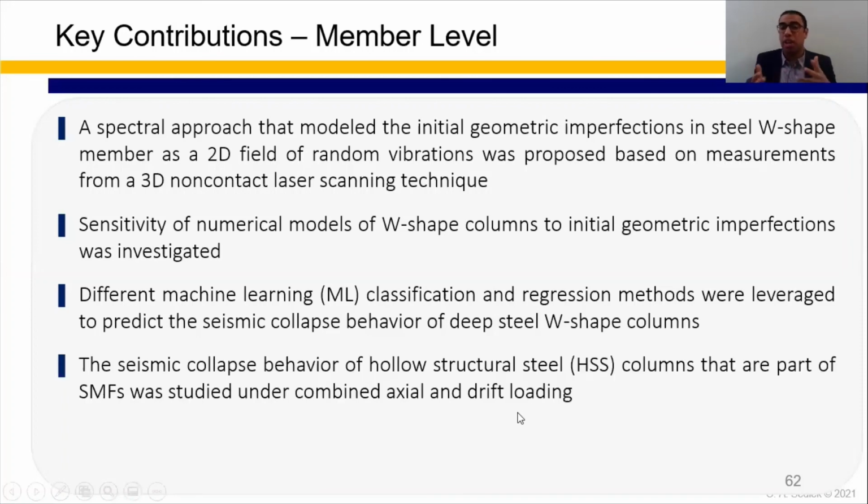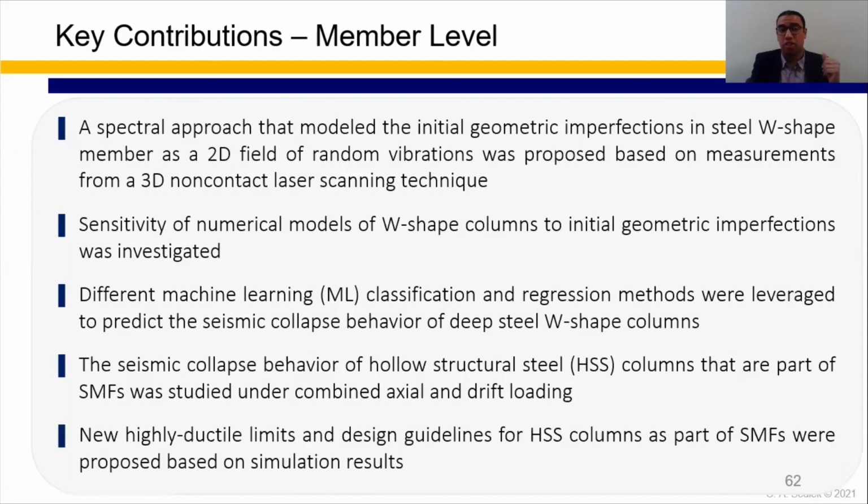Also the seismic collapse behavior of HSS columns that are part of special moment frames was studied, as I showed, under combined axial and lateral drift. And based on the simulation results, new highly ductile limits and design guidelines for HSS columns as part of special moment frames were proposed.